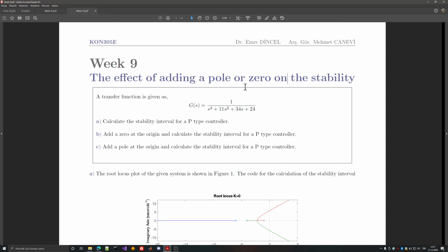And I can generally say that adding zeros increases stability. Adding a pole at the origin will decrease the stability. So basically, you're trying to add 2 zeros, and you have the pole, you choose a gain, and you're good to go with the PID controller. There are also different structures like the PI-PD controller, where you use the PD controller, place the zero, but the zero doesn't affect the system, and it's more likely a PI controller with more freedom.